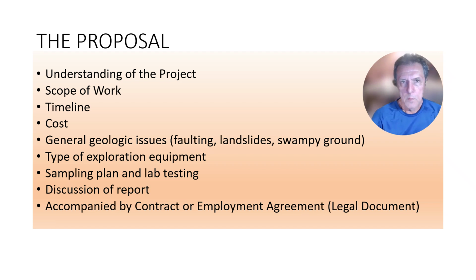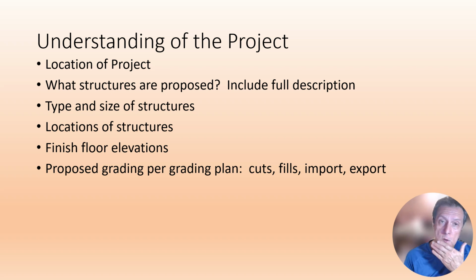Okay, you submitted your proposal to the client, and you've made him or her aware that you have an understanding of the project, which is going to guide your investigation work. Where is the project located? What are the structures proposed? Include a full description in your proposal. Is it a skyscraper? Is it a bridge? Is it a roadway? Is it single family homes? Type and size of structures, locations of the structures relative to the property.